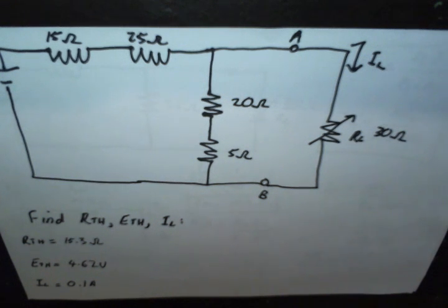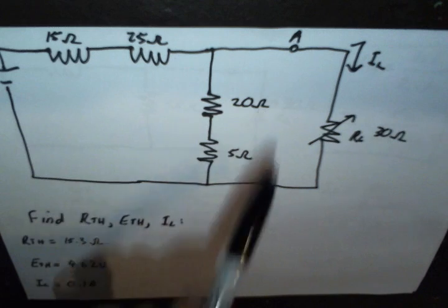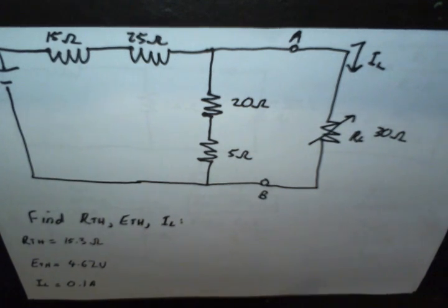Today we'll be discussing Thevenin's theorem, how to apply it, and its significance in circuit analysis in our world today. Thevenin's theorem allows complex open-terminal circuits to be reduced into a much simpler form. The Thevenin equivalent voltage and resistance to the left of the open terminals is equal to the voltage and resistance of a load-bearing resistor. Using Thevenin's theorem, any two-terminal DC network can be reduced to an equivalent circuit consisting only